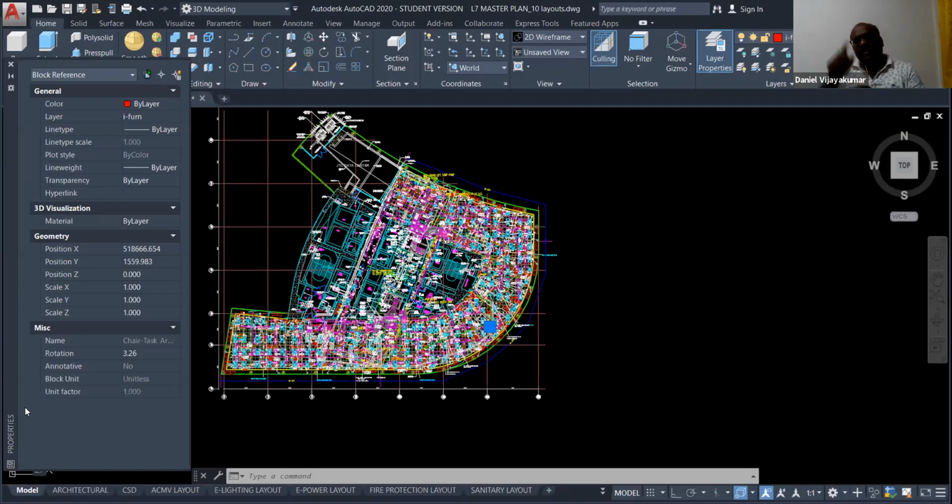For example, if you create a 100 mm square and you take the printout to the people, they don't know whether it's a 100 mm scale or 150 mm scale. If you have mentioned the dimension in the width and the height, they can easily know that the square is 100 mm. If you didn't mention the annotation, the value of dimension, they will not know that.